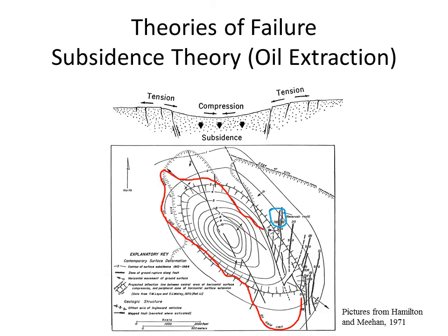In this figure, the red line represents the oil field and the blue line represents the location of the Baldwin Hills Reservoir. According to the subsidence theory, the downdrag and stretching pressure will be distributed along the ring of the subsidence area, shown with the orange line in the figure. In objection to that, almost all the rupturing has occurred in one limited section of the Baldwin circumference, which is shown with the purple line.